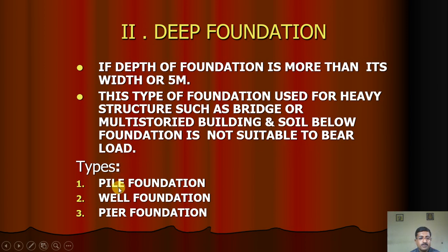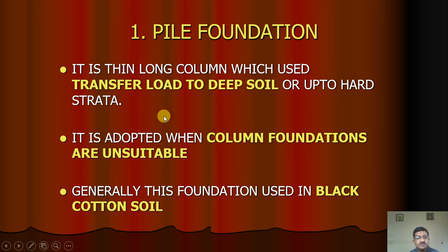Types are pile foundation, well foundation, and pier foundation. Pile foundation: it is a thin long column which is used to transfer the load to deep soil or up to hard strata. It is adopted when column foundations are unsuitable.